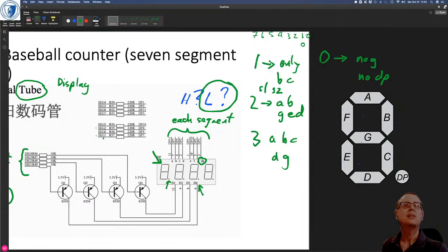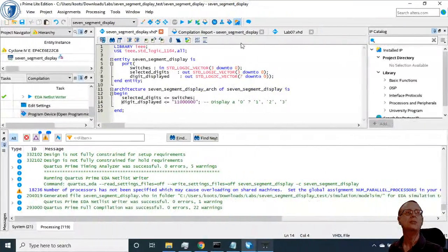And we need to select segment 2, so we need a 0 there. Remember again, this is all active low. So those two are the active ones. And that's going to be the second least significant bit and the third least significant bit zeros, and everybody else ones. So let's try that.